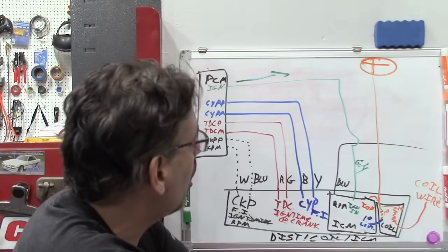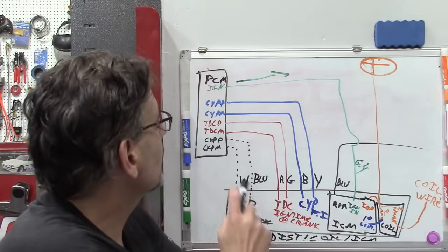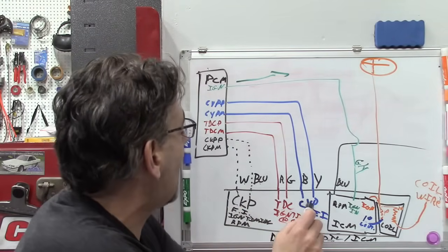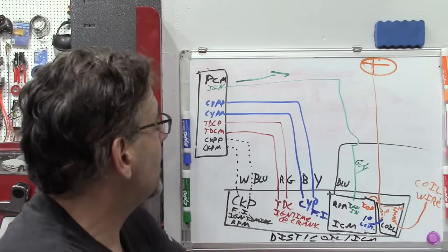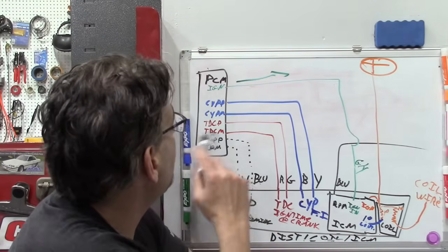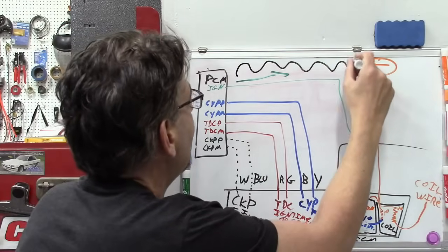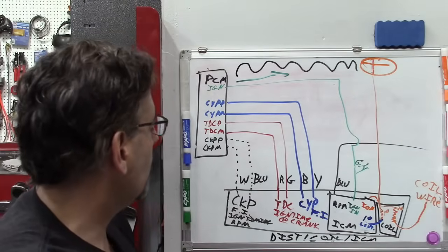Just to understand the system better though, I do want to look at these outputs and verify, because again, I'm expecting these are going to be inductive sensors, and we should see that kind of oscillating wave if we looked on a scope.